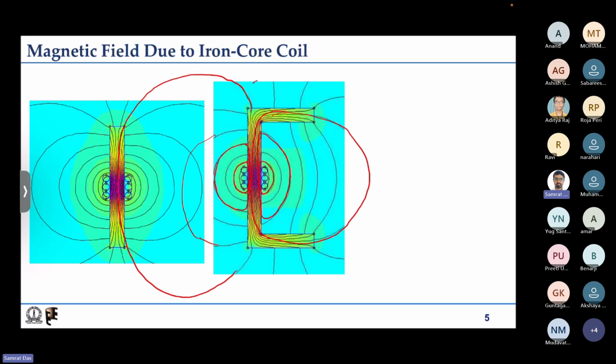That is what gives us this picture that iron has very high flux density. So I hope it clarifies the question. So first point, all the flux lines are closed, and because in air they tend to get distributed, that is why you have less flux density in air compared to iron. And because of very high permeability, all the flux lines are basically packed within the iron core.